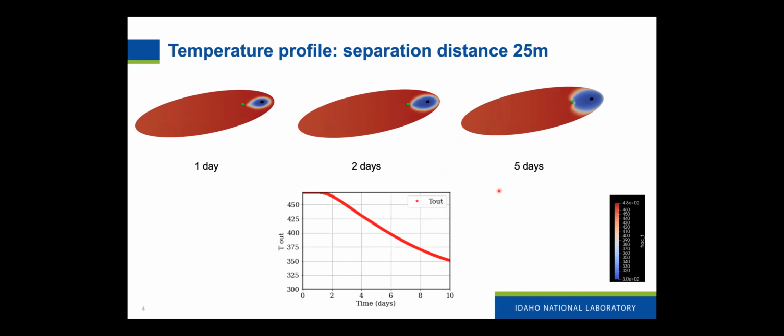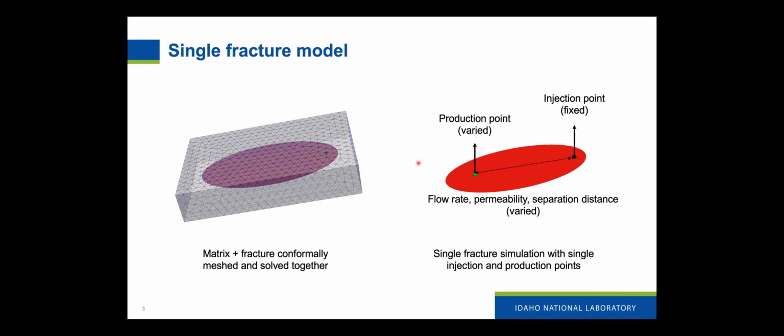So I'll mention the models, like a thermal hydraulic model. We have an equation of state for the fluid, and we have a fixed permeability. It's not a function of the pressure or the aperture or anything. And we're solving these together as a single simulation that's fully coupled. Not the multi-app stuff yet. So they are conformally matched, and we get good heat transfer between the matrix and the fracture.